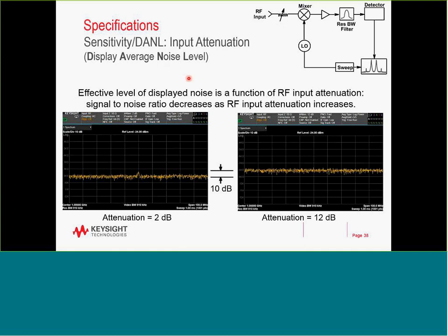This is directly impacted by the attenuator that you're using at the input. What we see here is that on the right side of this slide the attenuator is at 20 dB, and on this side it is at 0 dB, and you can see that we're gaining 10 dB of range, so this one has 10 dB more range than the previous one, just by lowering the attenuator.